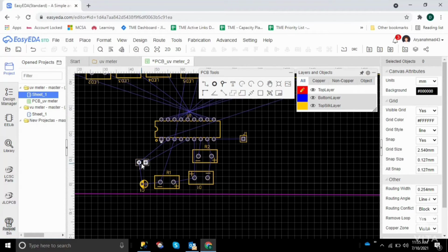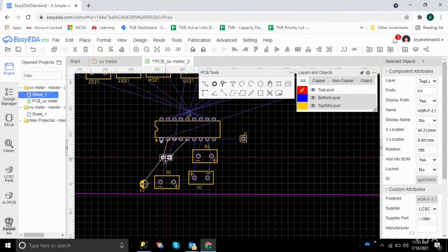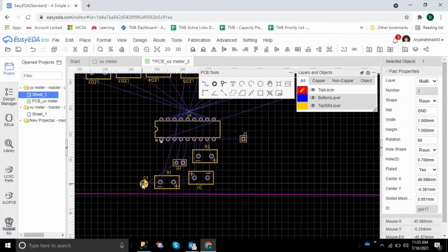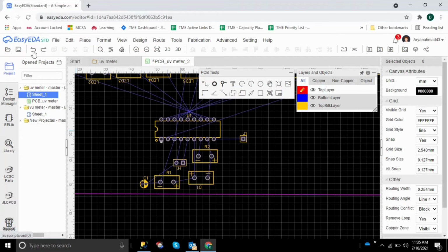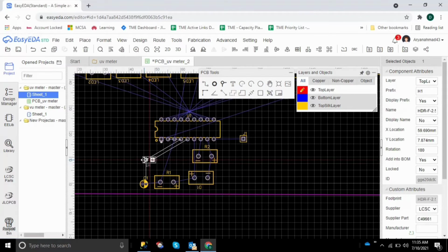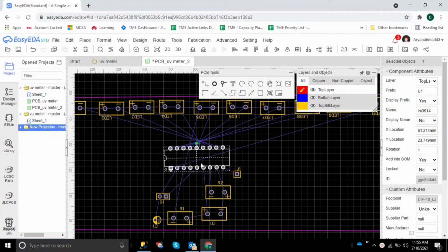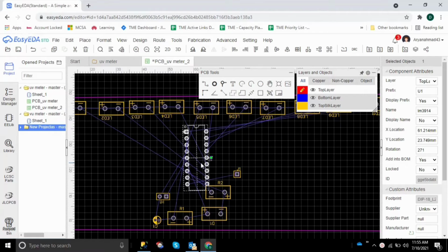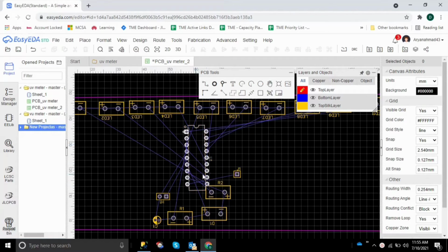So what I tend to do is place the center there, place like that. Replace back, because of what I have to do in the project. Now put the IC such like that, it will minimize the wire jumps. So you can see the layout minimizes the jumps.